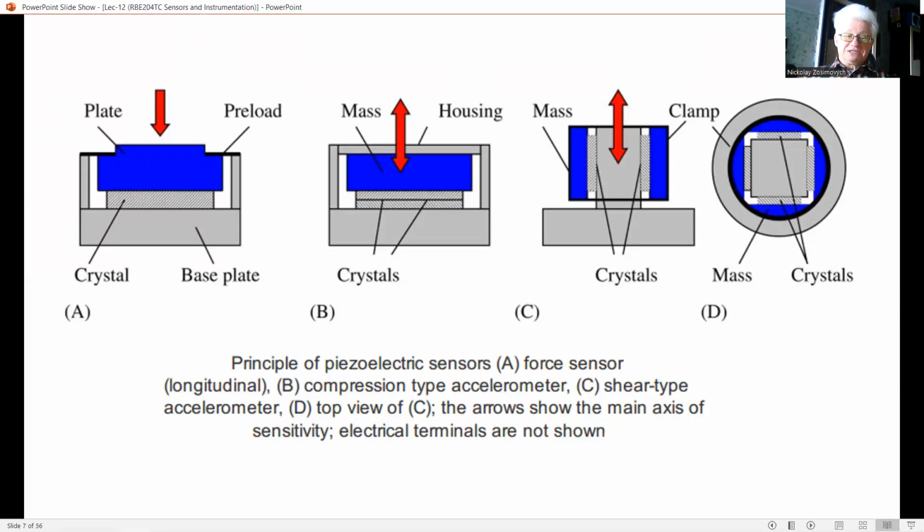Here the pressure sensors are also sensitive to acceleration, because the mass of the housing produces an inertial force on the crystal when accelerated. For applications where pressure has to be measured in a vibrating or otherwise moving environment, special pressure sensors are designed with a compensating crystal to minimize the acceleration sensitivity.